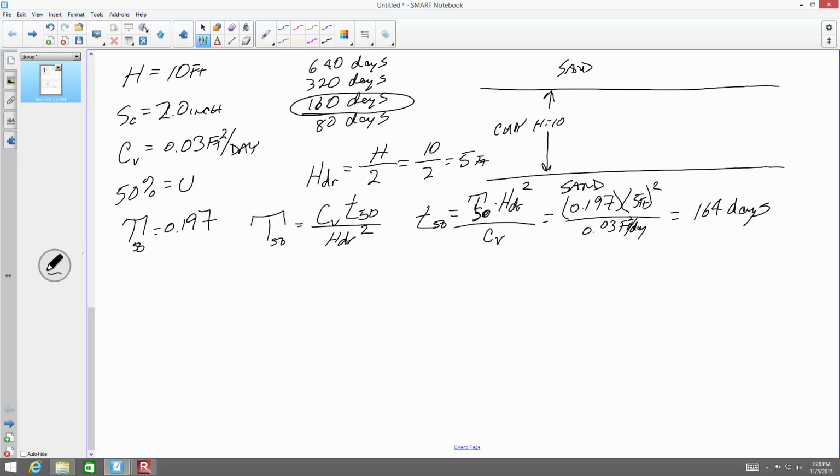Here we go. Do a little shear strength. We've got sand. Phi is 35 degrees. So that's a decent material. Tested in a direct shear test. The direct shear box is a 3-inch by 3-inch box, so it's a square box. I'm going to test it with a load on the top of that of 200 pounds.